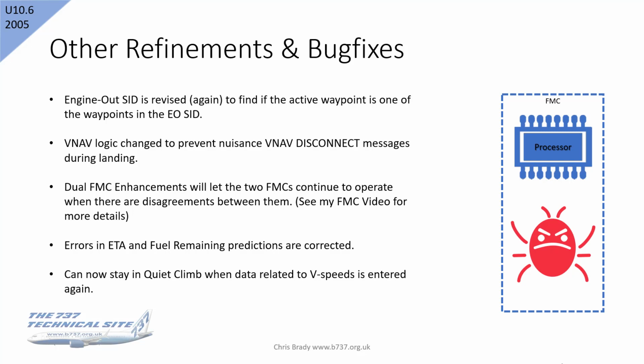Other refinements and bug fixes that came in with 10.6: the engine out SID logic was revised again to find if the active waypoint is one of the waypoints in the engine out SID, so it could connect seamlessly. VNAV logic was changed to prevent nuisance VNAV disconnect messages during landing, which was very much an irritant in the early days of the NG.